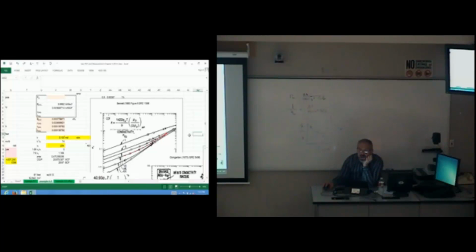So does the data prior to the first X show the variable storage? Not in this case. You notice all the data is on this line. So that line has no wellbore storage effects. You rarely see wellbore storage in a fractured well because it's like a negative skin. It overwhelms. There's so much easy flow into the wellbore.